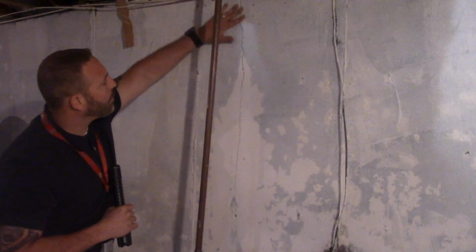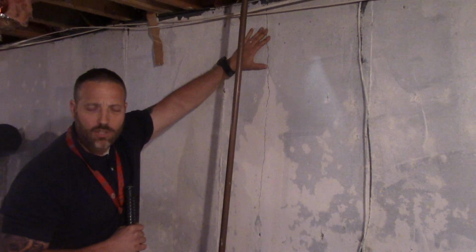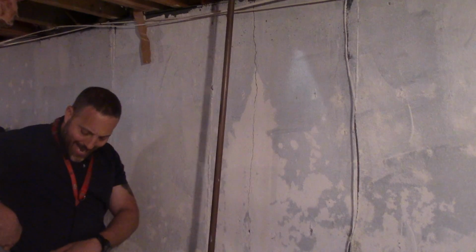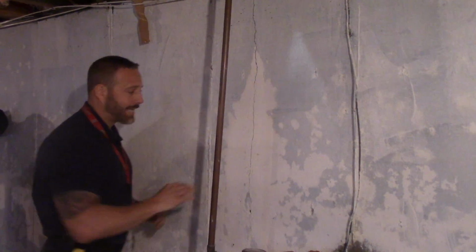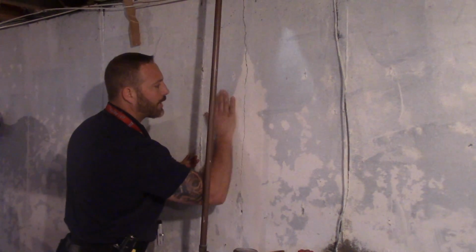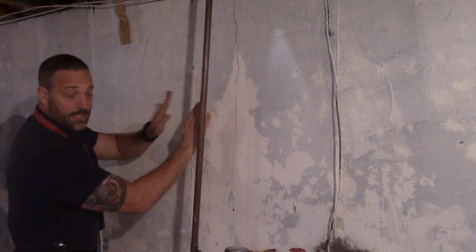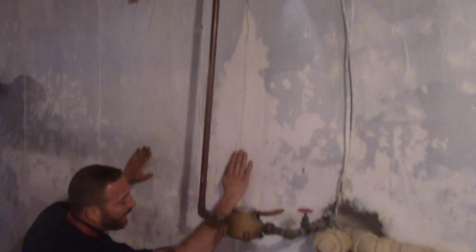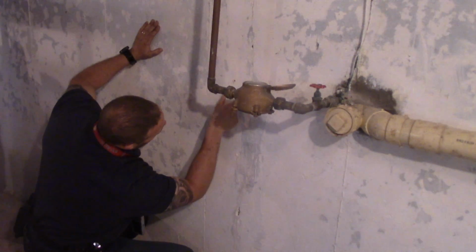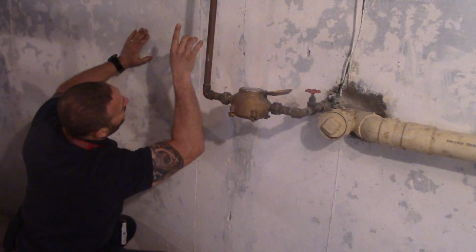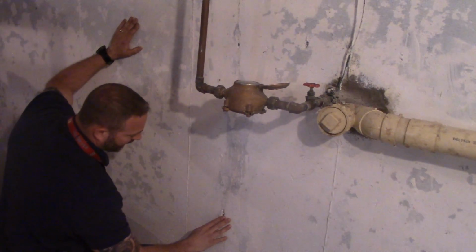Also, you can see where they painted. So there's still some movement in this vertical crack. What we end up doing when it comes to vertical cracks is we're going to feel that crack. And what I'm not feeling is any displacement. And as we go down, you can see that, all right, this has been patched up a little bit and it's been painted, so it's a little wider up there than down here.